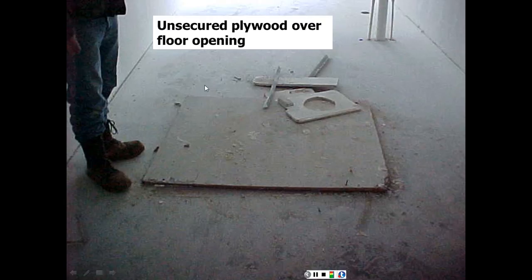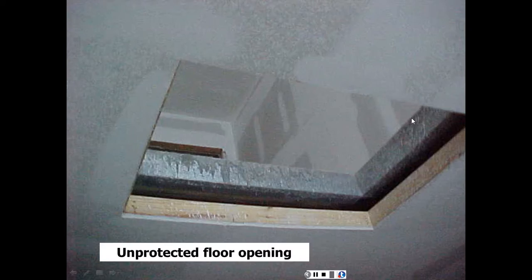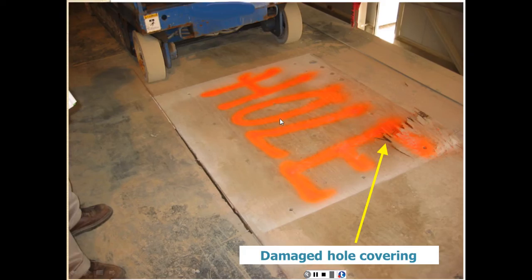Now this is a plywood cover. It doesn't seem strong enough to support the weight of a person, or twice the weight of a person, so this is not proper. This is an open hole. It's not protected. And again, the cover here, although it's marked as hole and everything, is plywood and it's damaged, so it definitely will not withstand twice the load that should be imposed on top of it. Same thing here. So this should be definitely replaced. Here the cover does not cover the whole area, so this is not going to work.